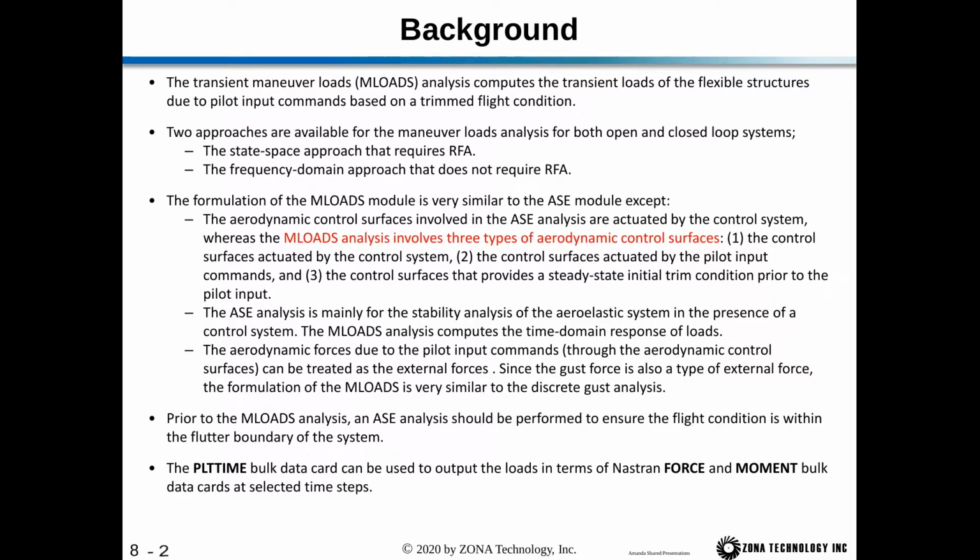And next, the aerodynamic forces due to the pilot input commands through the aerodynamic control surfaces can be treated as external forces. And also, since the gust force is a type of external force, the formulation of the MLOADS analysis is very similar to the discrete gust analysis. Now, prior to the MLOADS analysis, an ASE analysis should be performed to ensure that the flight condition is within the flutter boundary of the system.